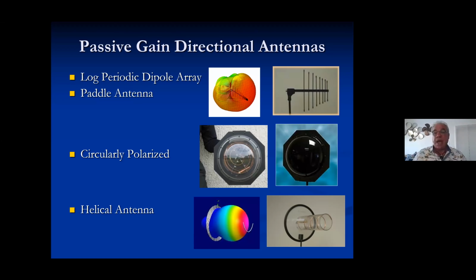And whenever you have an active RF device in any radio circuit, you can introduce intermodulation distortion, which we'll get into on the 22nd really deep. But the bottom line is a nonlinear device is required for RF signals to mix and match. And by nonlinear, you could have a rusty antenna creating an NP or PN junction. That's enough nonlinearity to create intermodulation distortion, or the active mixing of multiple RF signals.